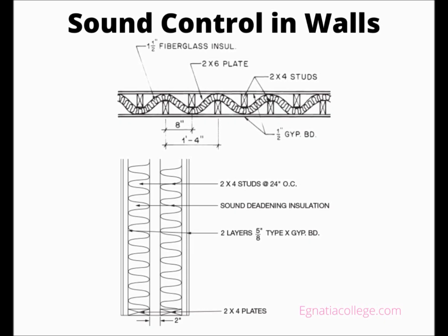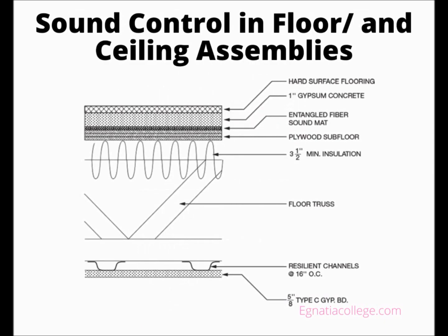Separating the two sides of the wall framing on separate plates and insulating both sides of the wall cavity yield an even higher STC rating. There are many other products and designs that can be used to control the sound transmission through a wall. It is essential that those who assemble common walls understand and follow the architect's design.